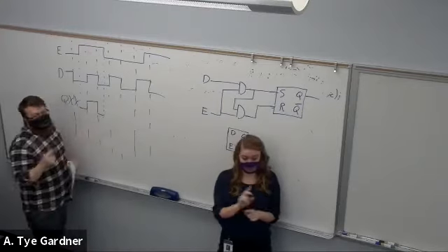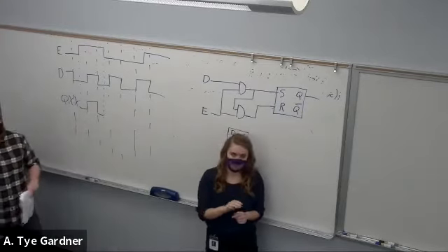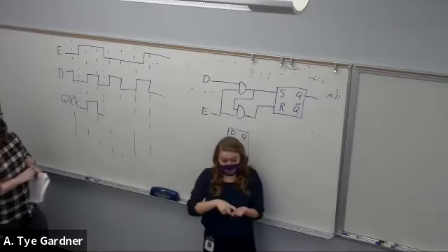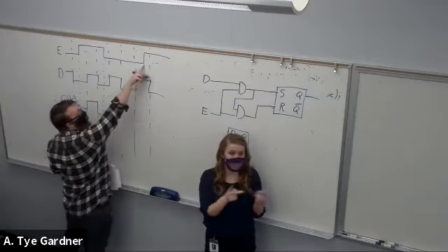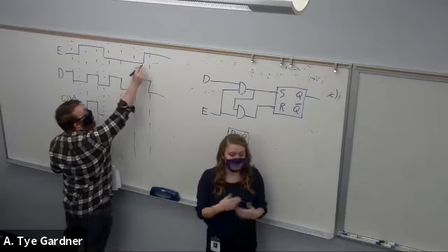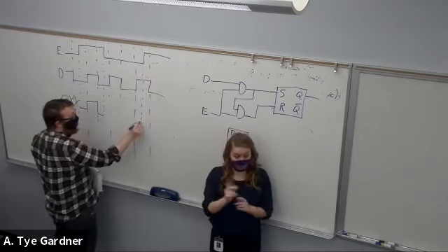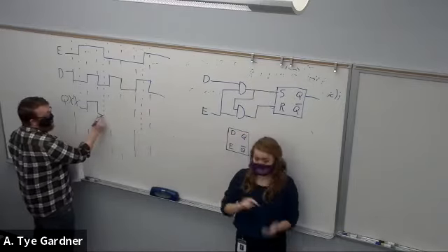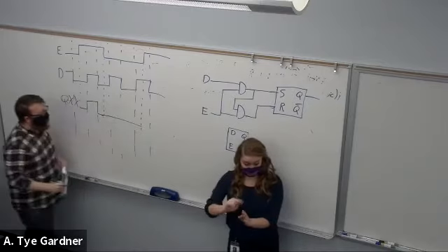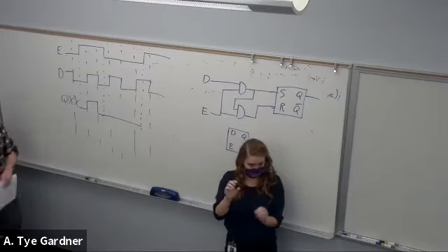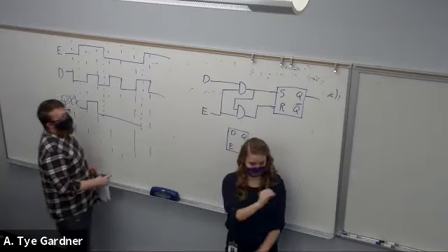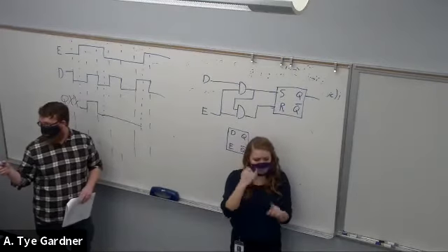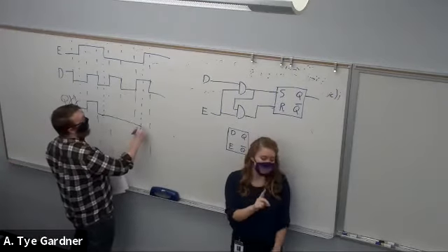And this is a good trick to pick up now, identify the locations where it's likely to actually respond. So I know because enable doesn't go positive, turn on, until this point, then I can't change. I hold a 0 all the way till then. All right, then it goes positive. What happens once it goes positive? It follows D. Exactly, yes, it just follows D.